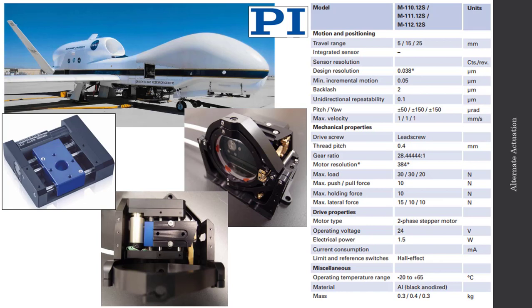Let's wrap up this lecture with a quick look at a unique application of stepper motors. Shown here is a wind LiDAR, an atmospheric LiDAR that flies on a high-altitude UAV. And this particular LiDAR, due to thermal gradients across the instrument from takeoff up to altitude, needs to be aligned periodically. So to accomplish that alignment, we built a tip-tilt mirror into the system.